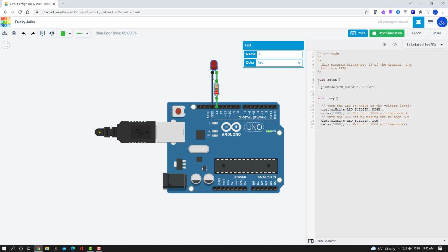And as we look at our LED here on the screen, we can see it lights up red and then dims, and we can see it lights up in unison with the onboard LED. This is really important because we can use this sketch at any point to ensure that our board is properly working. So when you pull out a board from the back and you bring it to your desk for the first time and it doesn't seem to work, sometimes it's a good idea just to run this blink sketch to make sure that the board is working, that it's accepting code from our computer, and that it has the ability to control this onboard LED.